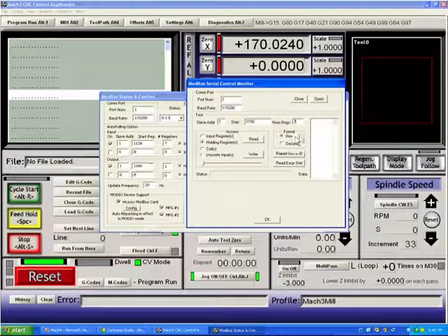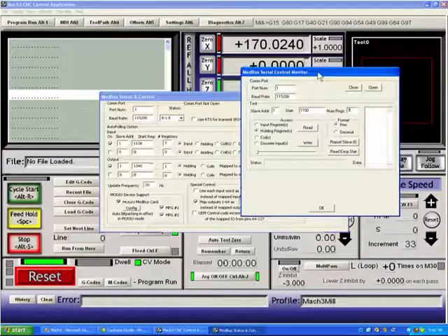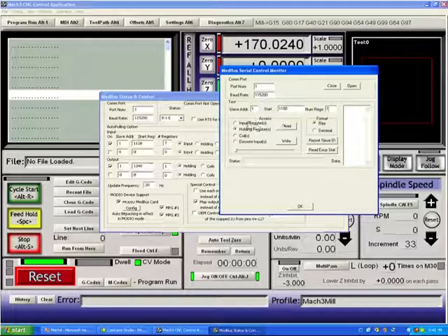that we can read. And we have to tell any ModBus device what we're reading. ModBuses have 4 general areas that we can read. They have input registers, holding registers, coil registers, and discrete input registers. In the case of devices that you're going to be reading from Peter's board, you would be reading the input registers.